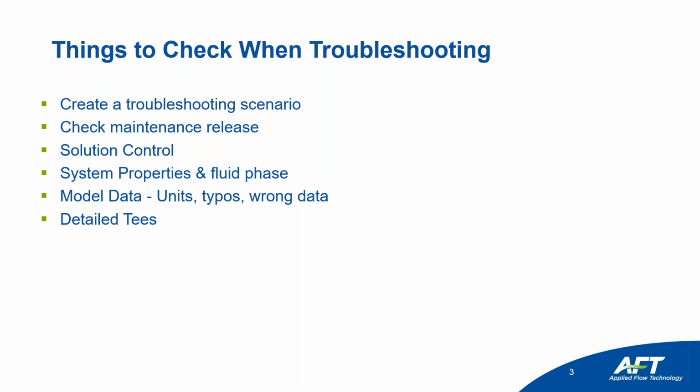And so typically in systems, the amount of frictional losses that your T's will add to your system are usually negligible in comparison to your other heavy loss components in the system, such as valves, orifice plates, long runs of pipe, heat exchangers, things like that.